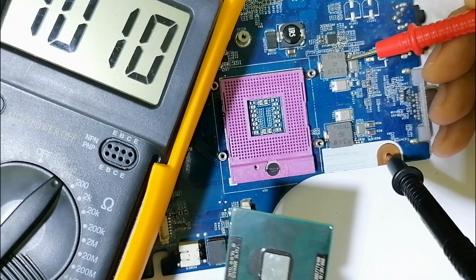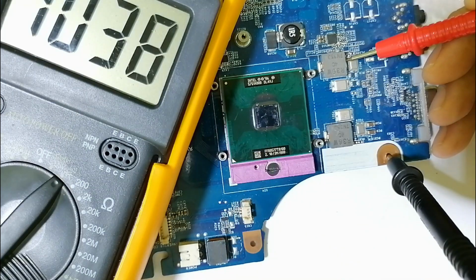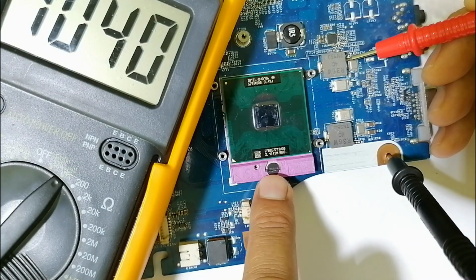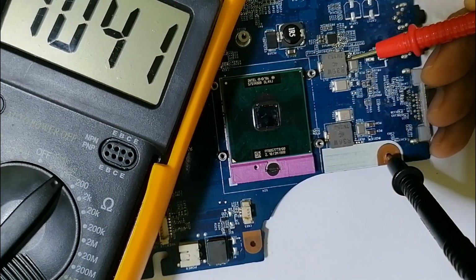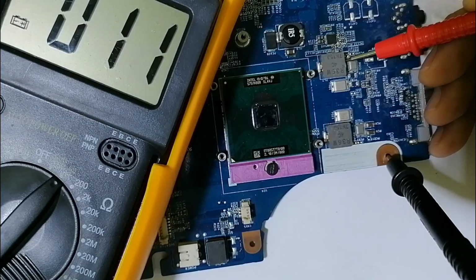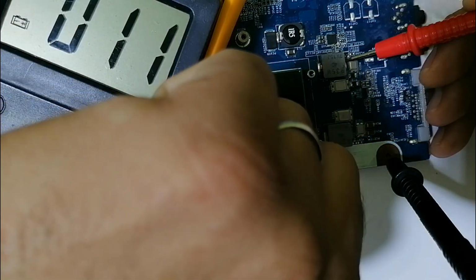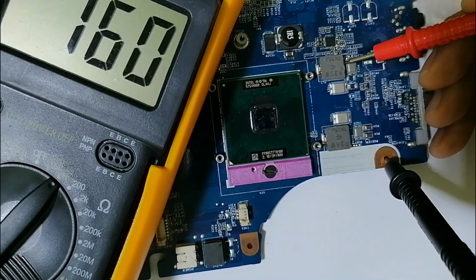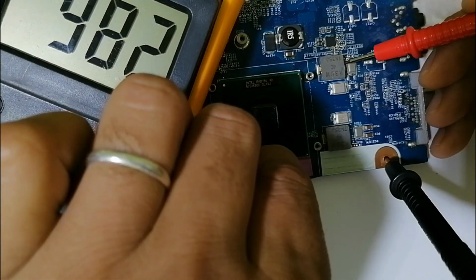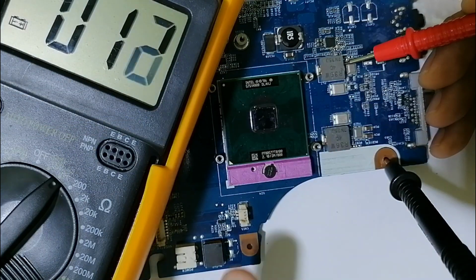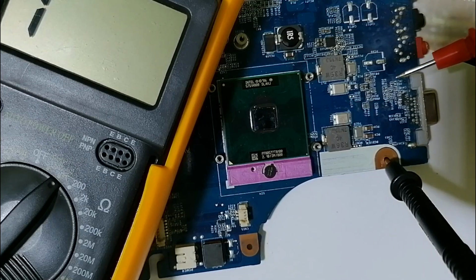So let's put the processor in its place. Now let's unscrew the screw, and you will see that the short is back. Do you see? Once I loosen the screw also, do you see? The short is gone. Basically, it's not a short, but it's the CPU resistance. Let's do it again for the last time. Do you see? When I close this one, the short is back.